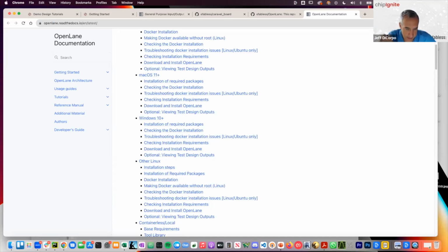I was commenting that it is one model that would work, and that would be recommended. It would be to implement your accelerator function and then implement the register set, or digital wrap, around that, which connects to the wishbone bus so that you can both provide data in and read data out from that macro.